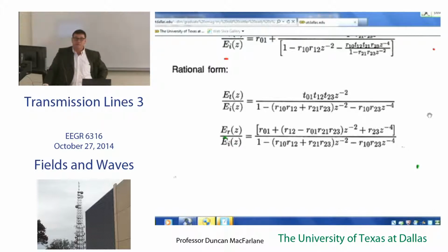Okay? So tremendously powerful set of tools once you make this pedagogical leap of recognizing the time of flight from one end of a transmission line to the other end as a z to the minus 1 or 2 or 10 or k coefficient of delay. Okay?